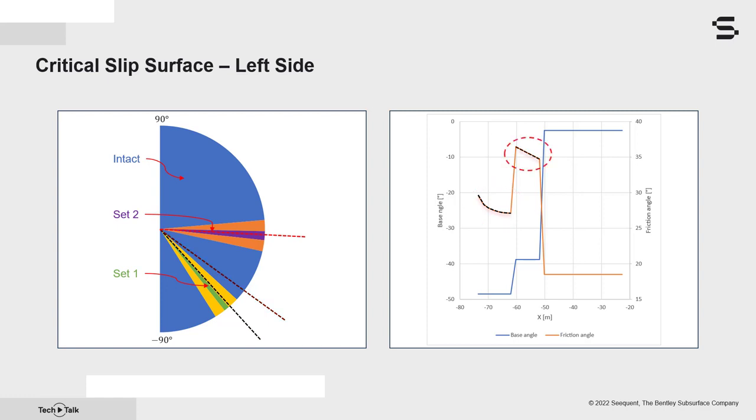For the middle portion of the slip surface, the mobilized friction angle only depends on the intact rock mass, which in this case uses the Hoek-Brown failure criteria. Finally, the friction angle for the last section of the slip surface only depends on the second joint set and is constant at 18.5 degrees per the Mohr-Coulomb material model it uses. This low friction angle is used for the greater part of the second half of the slip surface and influences the resulting slope stability.